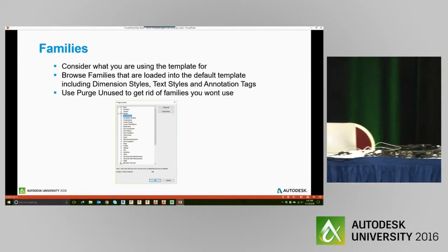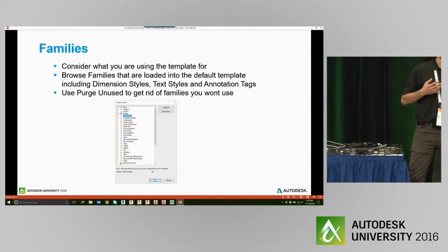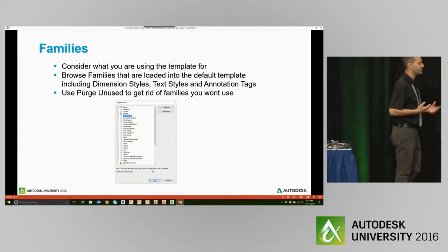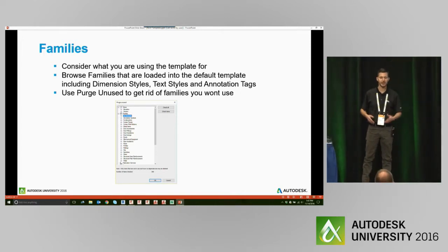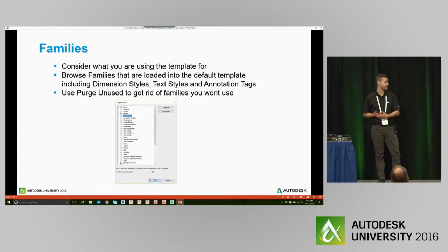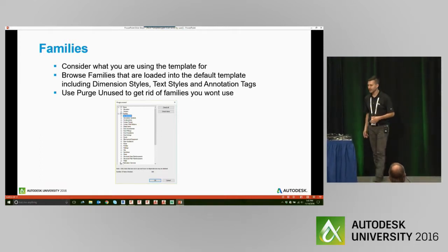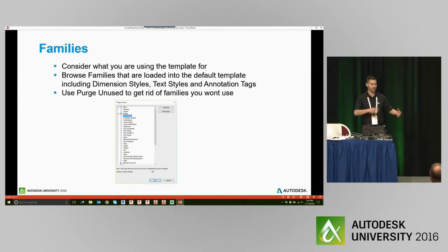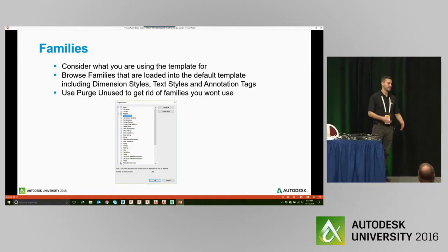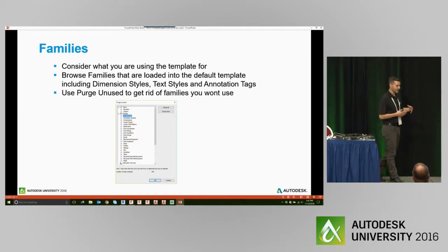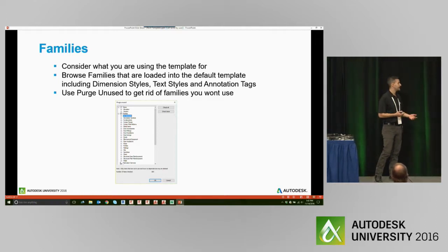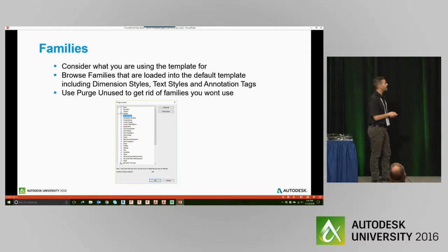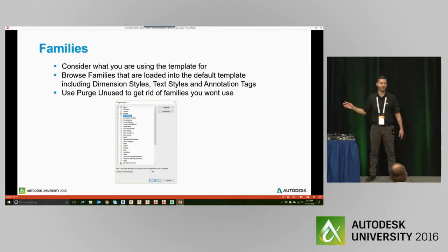He was saying pretty much you stick with the design elements, the actual families, as long as you can, and then convert those to the fabrication parts in Revit. Just because it's a lot easier to edit and move and push and pull and coordinate until you need to get to that design level or the fabrication level content. So again, we're going to be needing families, so you can't just go in and purge them all out.